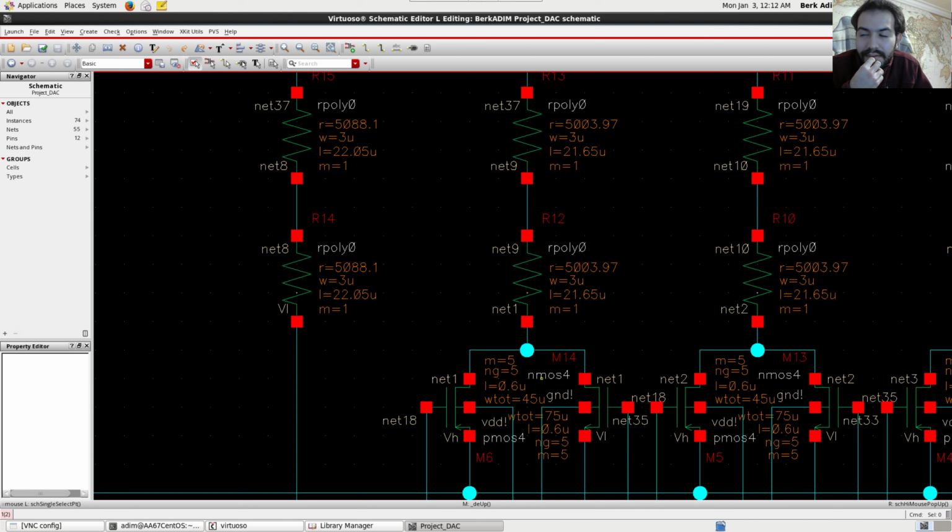Well, there is one problem there. That arrangement accounts for the resistances of the transistors, but it does not really account for the off-state capacitances the transistors bring into our ideal design. If you make the sizes quite different, you must make the PMOS device nearly as big as the NMOS to get equal resistance. But then the off-state capacitance of the PMOS ends up quite higher than the off-state capacitance of the NMOS.